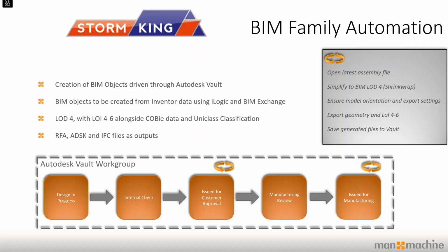So what we came up with as a solution for them was creation of the BIM objects driven through Vault. And we did this with a Vault lifecycle. Some of you may be familiar with Vault and its products. Maybe you use Vault Basic, which does come in the PDMC. But when we look at Vault Workgroup and Vault Pro, we have the option for lifecycles. So what we can then do is use your lifecycles to trigger certain actions.